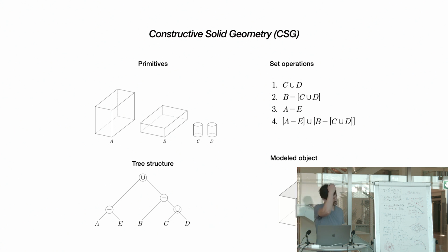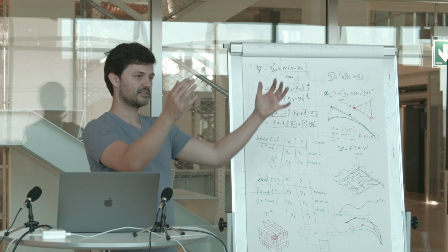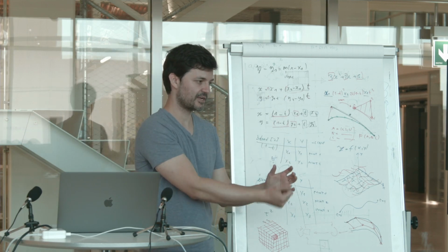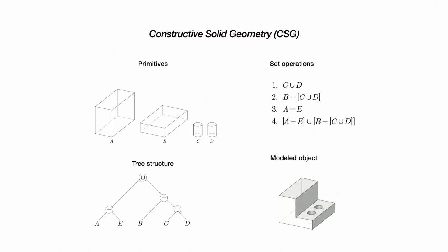Then another way of modeling, also solid modeling, resembles traditional additive and subtractive model making. For example, it resembles sculpting. You start removing parts until you are left with your object, this would be subtractive. Or another way, you start building from simple objects, putting them together like Lego to get something bigger. So you have some basic elements, building blocks, like box, pyramid, cylinder, sphere, and then you create complex shapes through functions like addition, subtraction, and so on, union. You model objects in the same way as you plan to produce them in the future. This is the idea. For example, you can subtract a cylinder from a box, and then you have a box which has a hole in it, stuff like that.